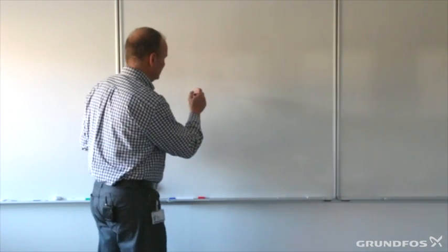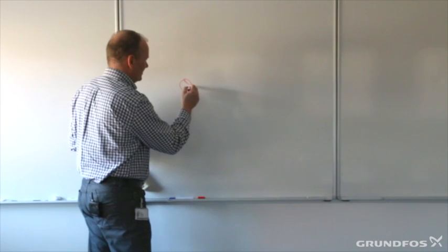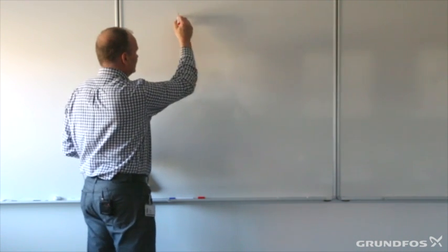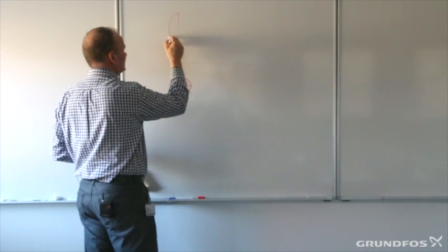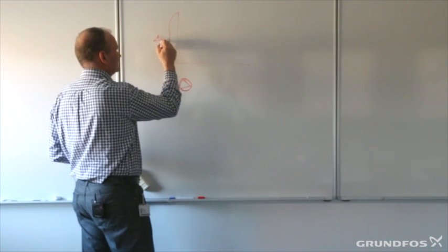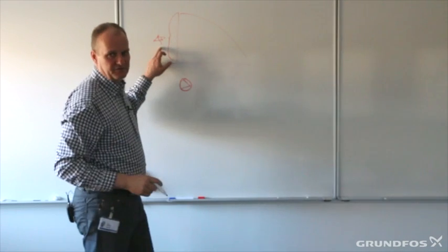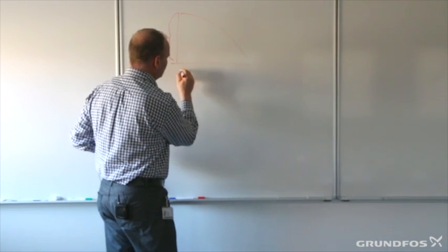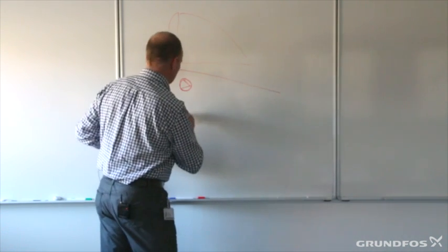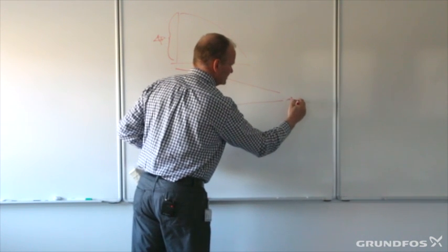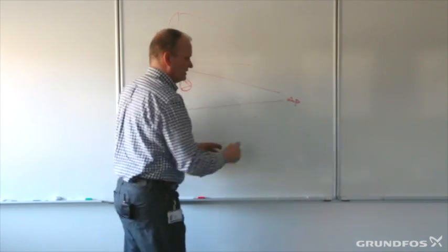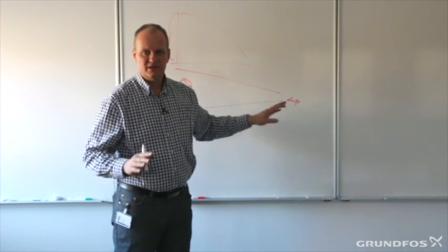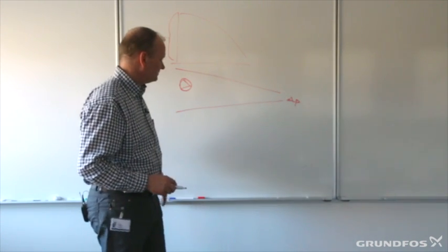If we have a pump operating in a system, we need to remember that what the pump is actually doing is providing the system with a certain level of differential pressure, delta P. And as we go out in the system, this delta P is decreasing until we reach the final consumer, radiator, air handling unit, whatever in the system. So the pressure is decreasing.